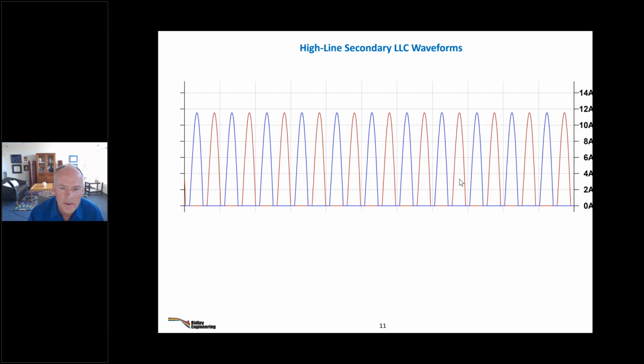All right. Dead time between the synchronous FETs, that's something that you tune in your circuit. In our simulation, we can open up the dead time, reduce the dead time, but you're going to do it in the hardware because that's all a function of the parasitic parameters on the switches, the diodes, and so on. They will affect the dead time. Don't expect a one-pass design on the subtleties like that. You have to tune the dead time that you need.